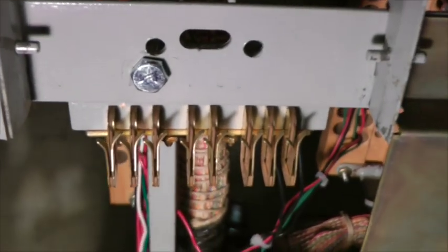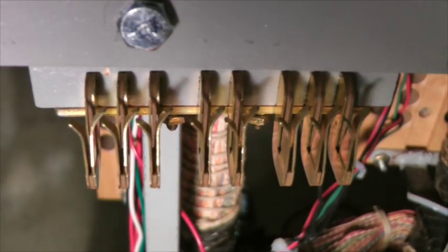On the line finder shelf, there is a corresponding set of 16 jack springs arranged in 8 pairs. The 2 jack springs in each pair are separated by an insulator, and the whole assembly is insulated from the framework by a wooden mounting block. The 8 line finder plug prong pairs line up with the 8 jack spring pairs, so when the line finder is in position, each plug prong pair fits tightly between the 2 jack springs of a pair, such that there is electrical conductivity between each prong and its mated jack spring.